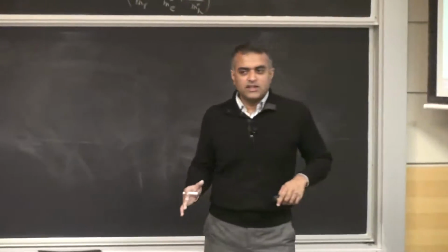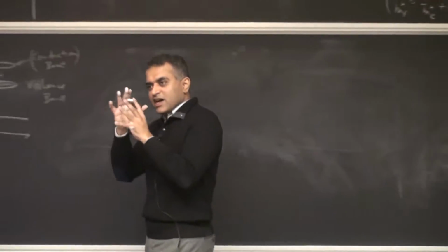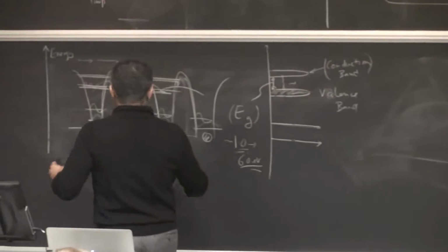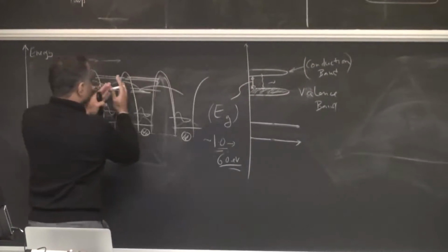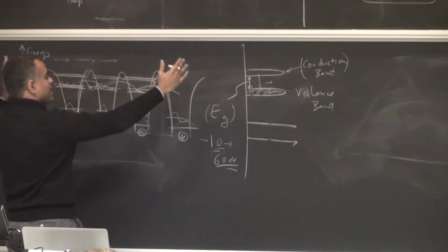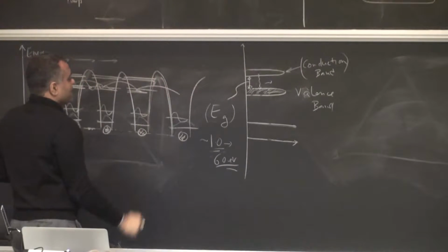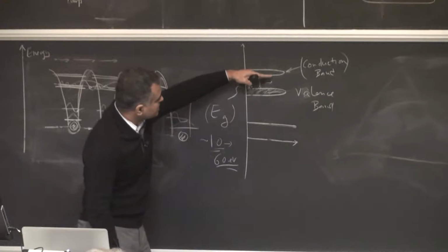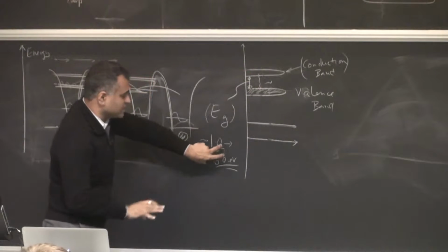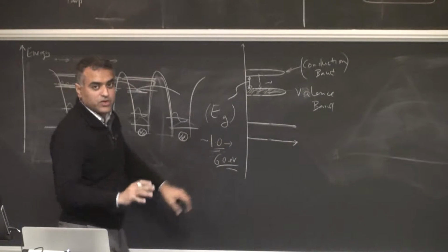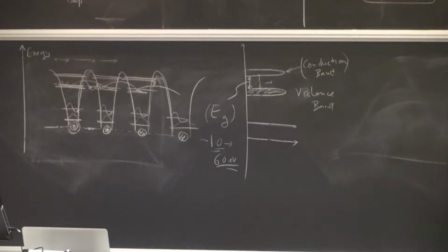You can't really mess with that. But in a semiconductor, by changing the size or the dimension of it, because these energies depend upon the size of the crystal, how far can the electron move freely, am I confined, am I mobile? Because of the energy, you can control it or engineer it. And therefore, you can engineer with the same material different wavelengths of emission. It's a very important property of semiconductor lasers.